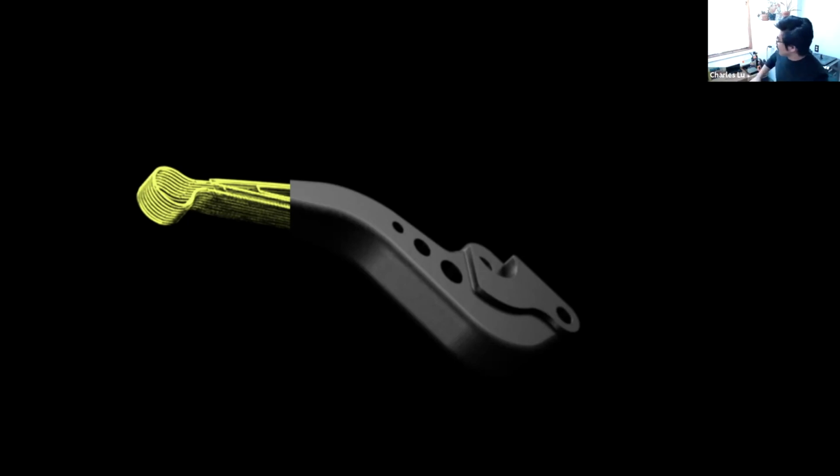I just like to have it run PLA. Maybe PETG, but I wouldn't run the Onyx on it unless I wanted it to have an early end to its career. Maybe with some swapping of materials, or if I were okay with getting new print heads every once in a while, it would be fine. But you need to upgrade the extruder hob and the nozzles, and then you have to make sure that you have a source for all those. So I'd be cautious about that, but you certainly can.